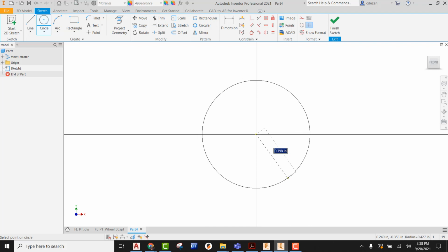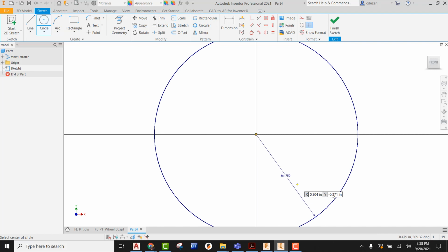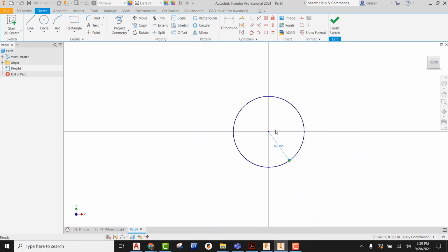Now we can even see how this has changed a little bit. Now it's asking for radius, so I'm going to type in DIA times 0.5. It says in the cam dimension drawing that a radius is going to equal half the diameter, so it's just going to be diameter times 0.5. I hit enter. We can see the fx is indicating that this is referencing one of the parameters I set up earlier. And it's telling us it's going to be half of that, which would be 0.75.